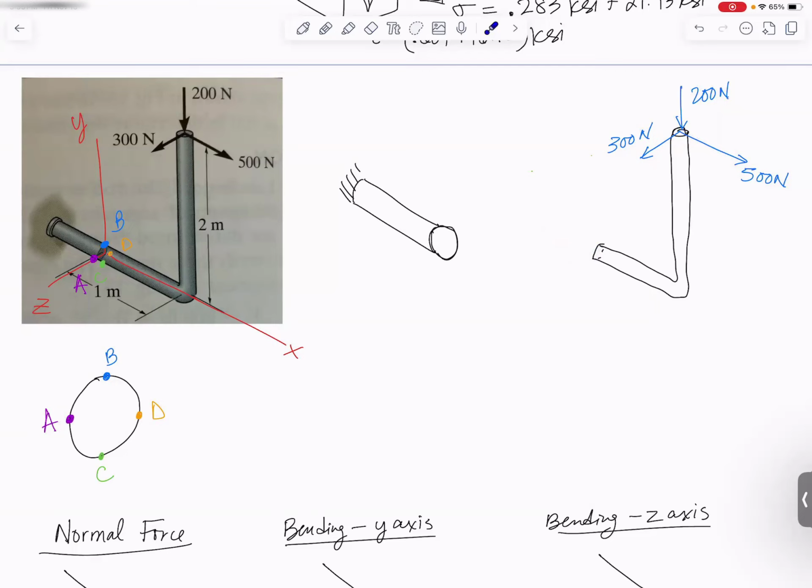Now, I don't actually like using the free body diagram for purposes of doing three-dimensional internal loads. And here's why. It's because that face right there is actually hidden from view. So here's a little shortcut. Instead of drawing, I mean, we can go ahead and draw it on here as well. Instead of drawing everything equal and opposite, we have a downward 200 Newton, so we'll have an upward 200 Newton so that when we sum forces in what I'm calling the y direction, they all add up to 0. Well, look, when I cut something open and I draw both sides of the cut, this upward force will have to have an equal and opposite pair on this other face that is pointed exactly downward, 200 Newtons.